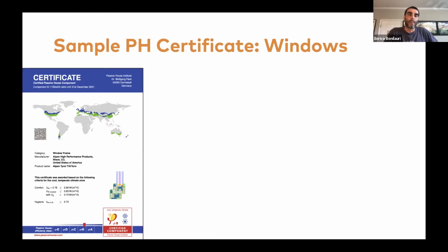And so there's a common belief that a triple pane window equals Passivhaus suitable, and that a Passivhaus window needs to have triple pane. And that assumption is partially true and partially false. So the certificate actually shows the comfort criterion for a specific climate.